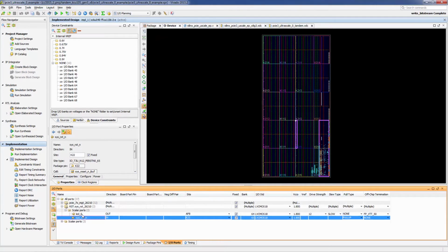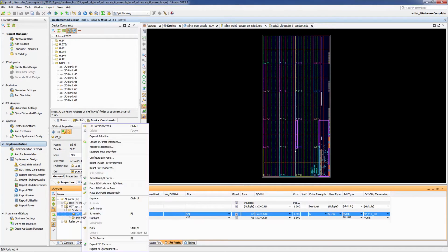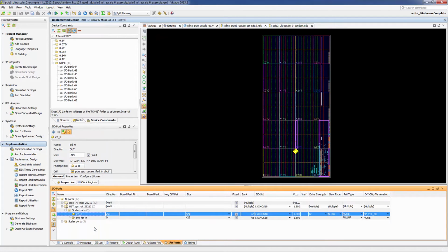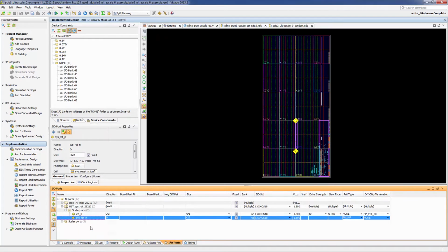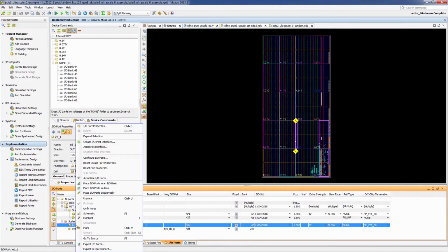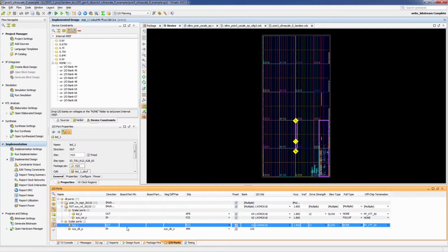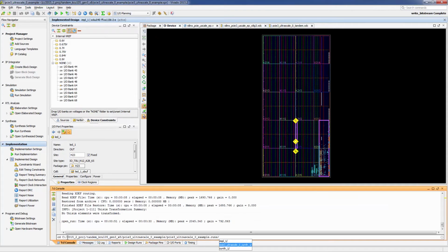And so you see LED 0 does not sit in that IOB, so that LED is actually going to be unconfigured to start. But then reset and LED 1 both sit in that bank 65. Those will both be configured, and so they, especially the outputs, may glitch. Now if you look at the product guide for PCI Express, you can find information on how to make it so that those outputs don't glitch if that's a concern. Since it's an LED, we don't really care.